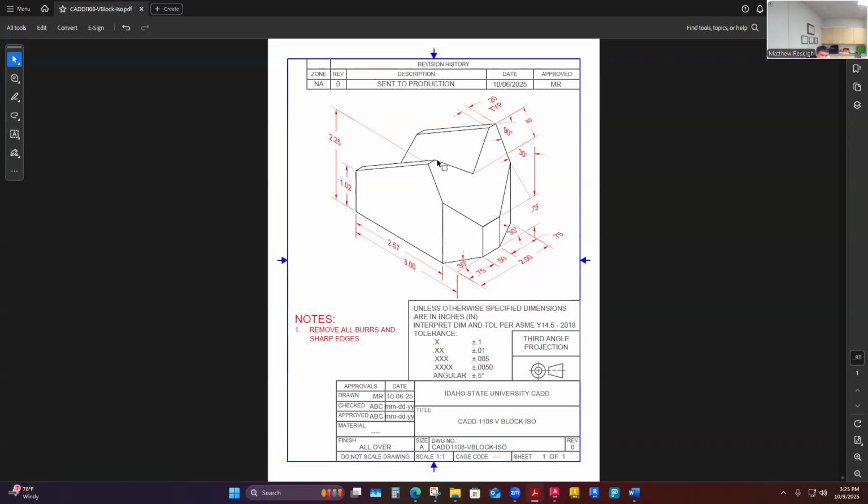Yeah, and even in my top view, this is going to be a foreshortened distance as well. I'm going to be looking down on it, but it's sloping down and away from me towards the middle. And so as I start to analyze edges and lengths, I start to see, man, some of these views are going to have a lot of data that isn't dimensionable. It's going to have the shape, and it's going to look like a top and front, but it's not going to have dimensionable sides for a lot of these things that I need to know. And so that's foreshortened anyway.